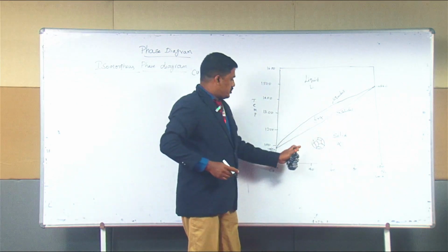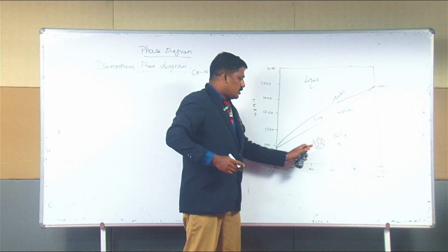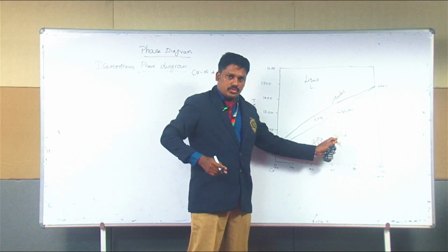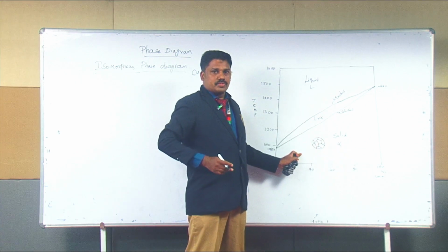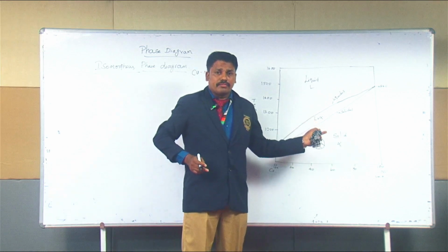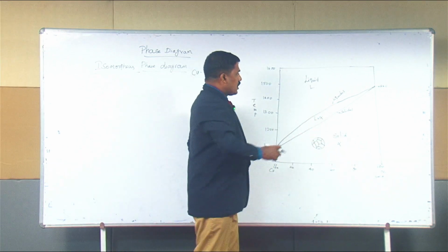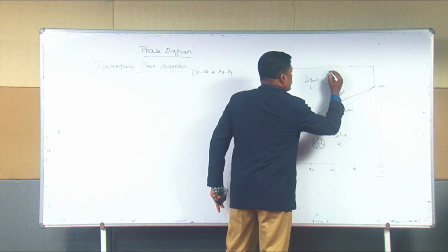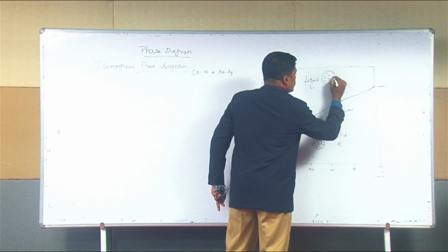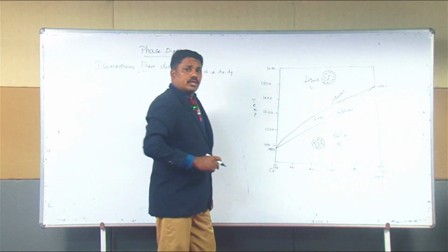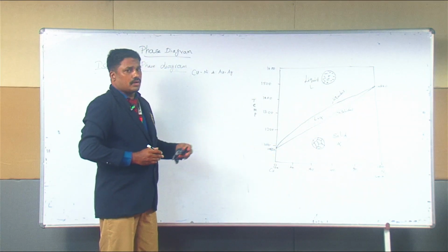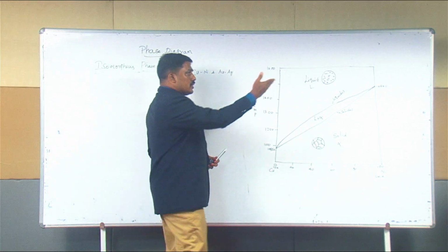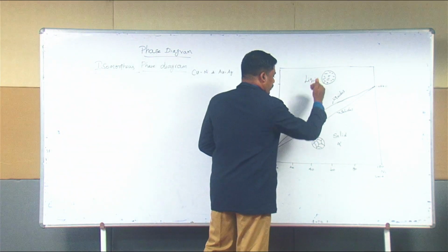Within this range, the components exhibit solid solubility, and since both have the same crystal structure, it produces a single solid phase. There are no different phases. In the liquid state, nickel is completely dissolved in the copper, or replaces the copper atoms, so it produces the same crystal structure in liquid and solid state.